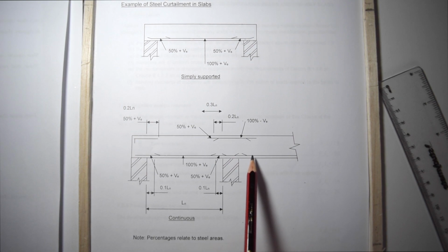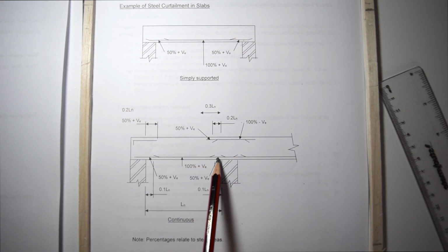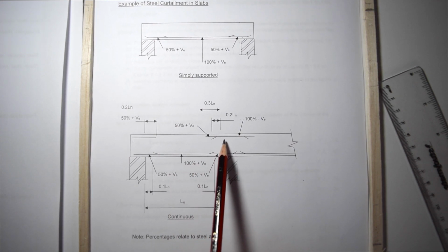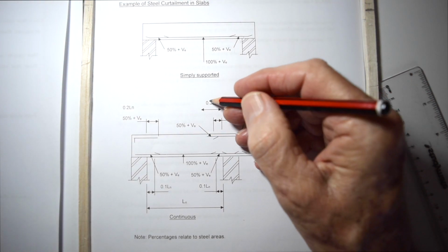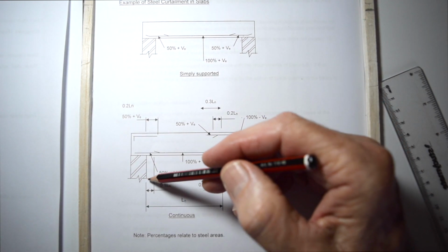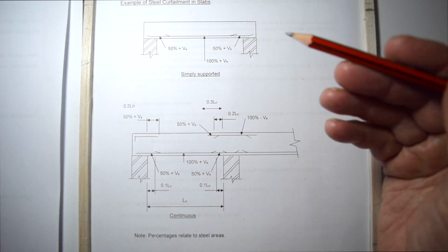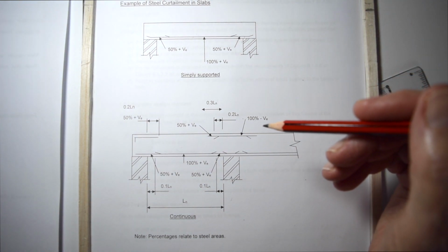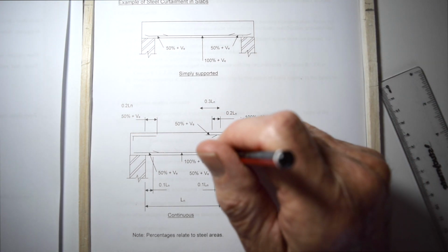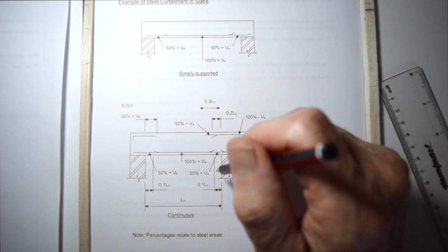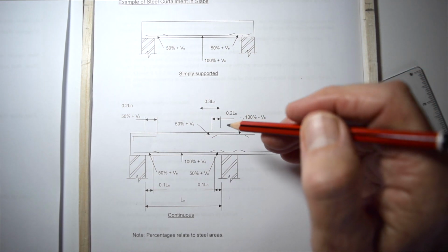Looking at a continuous slab, which is what we'll be having a look at today as well in the tutorial, a 3-span beam, these are the dimensions. Your negative steel must run into the span by a distance of 0.3 of this clear dimension. I usually just work to the centers of the supports, which is adequate as far as I'm concerned, but strictly speaking, you should work from the face of the support for a distance of 0.3 of that dimension, if you know the width of your supports and so forth.